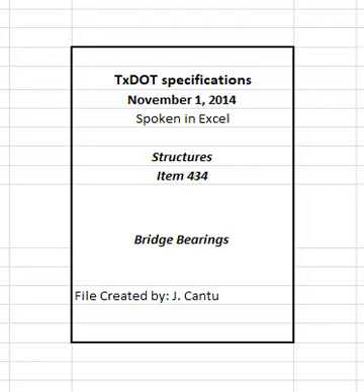3.1.2 Testing and Acceptance. The sampling and testing of laminated bearing production, after pre-qualification approval, will be as follows. 3.1.2.1 Laminated bearings. Subject each laminated bearing to a compression of 2250 psi or a stress approved by the engineer. Provide calibrated equipment per ASTM E4 for this compression testing. Each bearing will be acceptable if there is no visible evidence of bond failure or other damage and if the finished bearing meets other pertinent portions of this item. Samples may be taken if the quality of production becomes questionable.